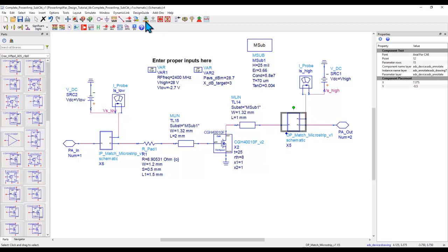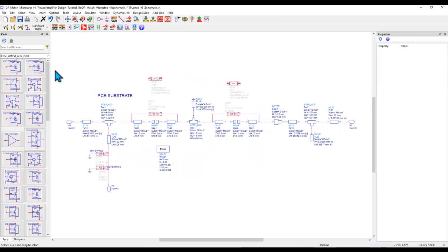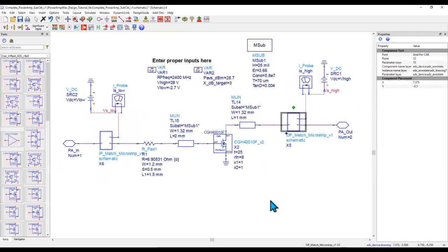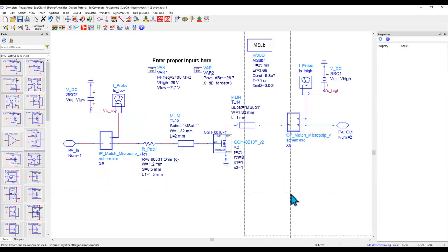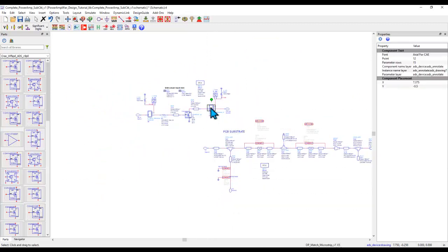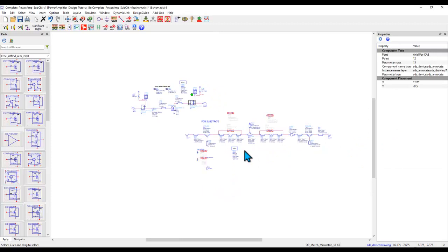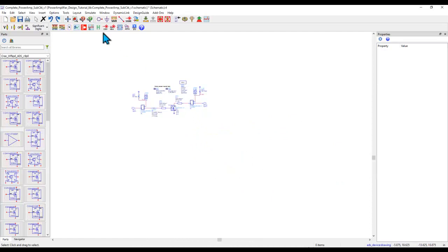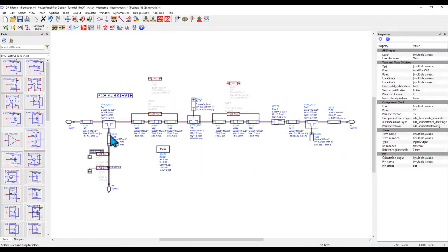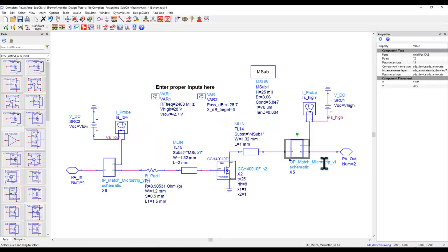So essentially what it means is you have gone in, taken all these components and removed them from the hierarchy, and you have placed them in the main design, something like this. So now this does not exist in your actual layout. This is the structure which you have. What I did was just for explanation, to let you know that everything from inside is gone because that hierarchy is broken.